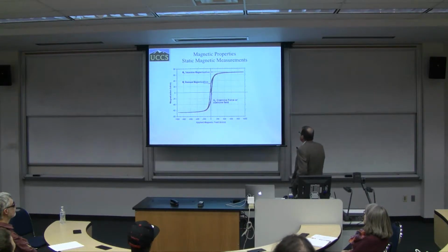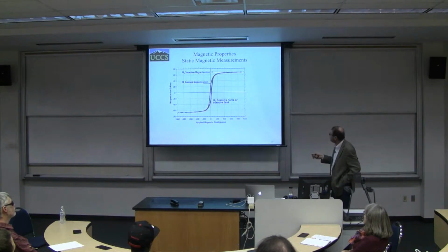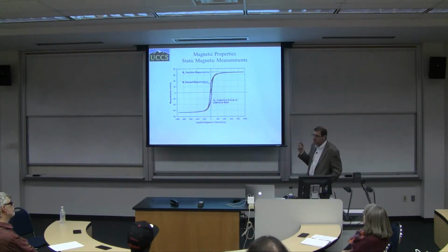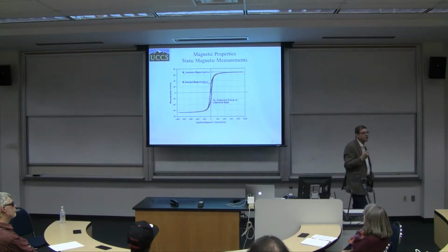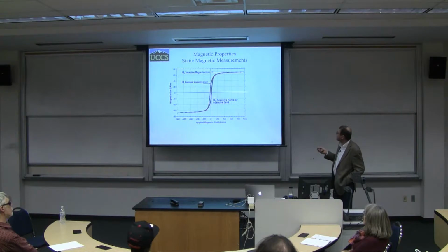If you have a hysteresis loop, which is basically what you measure for a magnetic material as a function of the applied field, you have something called saturation, which I talked about, and something called remanence. The remanence simply tells you the value of magnetization after you went from high field to zero field. For some applications, you would like to have this hysteresis loop without any surface area.